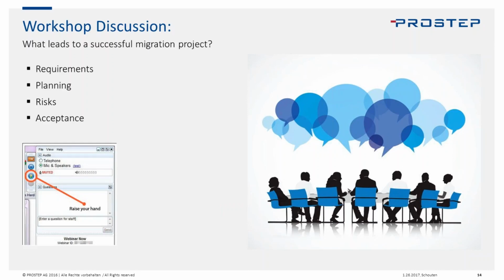Sometimes if you want to keep both systems, do an in-place upgrade of the Teamcenter environments and test out the integration that goes in the Teamcenter environment. You might have changed your document model or something like that between those systems, and make sure that stuff works within the test and the upgrade and the integration before going live. Hopefully I answered your question, but that's what I would see: in-place upgrade and good regression testing on the integration.